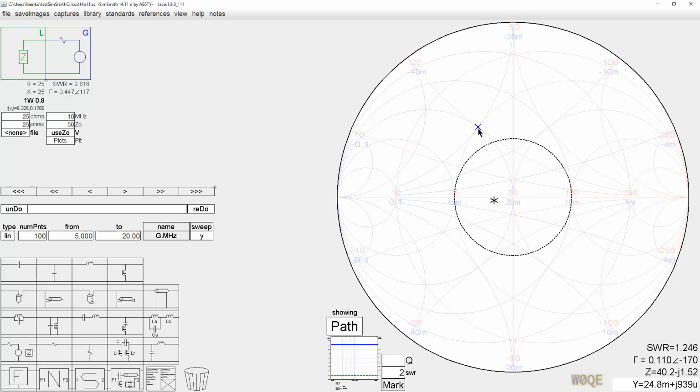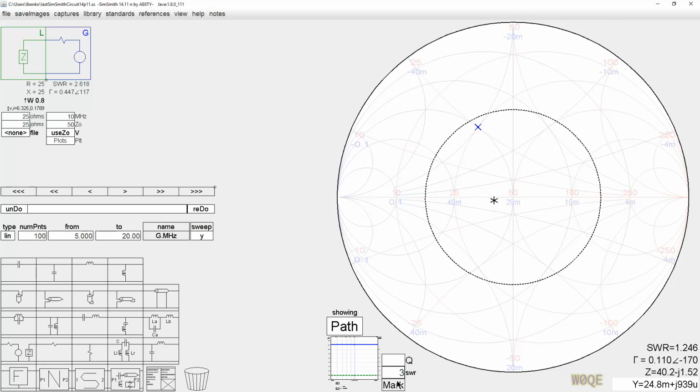The Smith chart has been called the chart of circles at various times because every one of these lines on here is part of a circle of some radius. You can think of the 2 vertical and horizontal lines as the radius of infinity, but all the rest are parts of circles of radii that are less than infinity. And while it's not shown on here, there's a whole bunch of radial circles, and they represent constant SWRs. There's one shown right now, which is 2. If I want that to be 3, I can just enter a new value in there, and that's a 3-to-1 SWR.